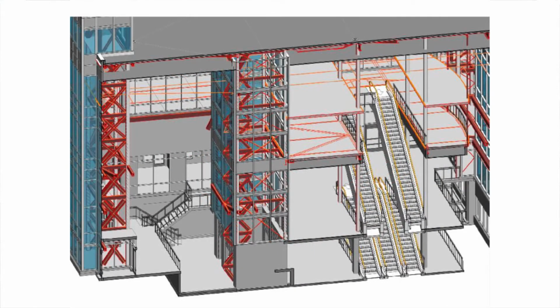Again, this here at Maple Leaf Gardens, very quick to see. Quite a big component of this structure of Maple Leaf Gardens, the renovations were all the stands, all the columns were all integrated into the exterior. So we had to do quite a bit of temporary bracing, shoring. So you're basically shoring up your system, demolishing it, re-supporting it, and then taking down this temporary stuff.